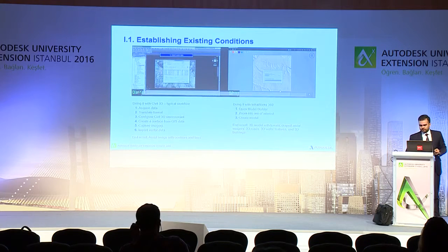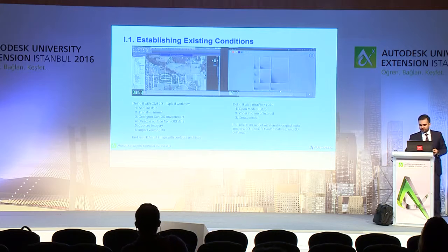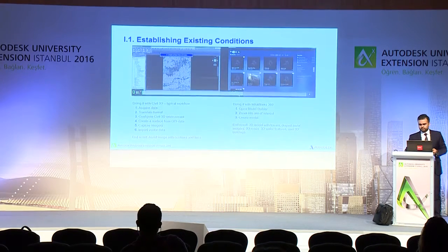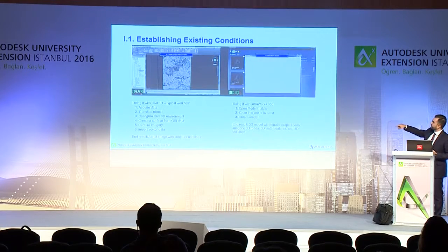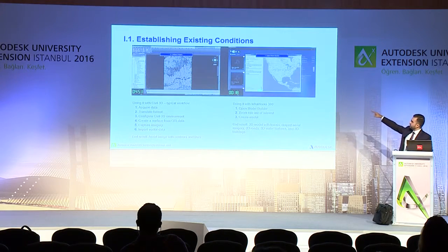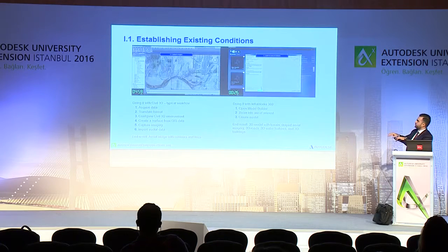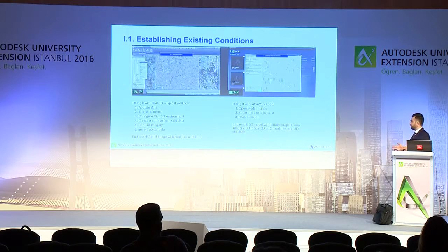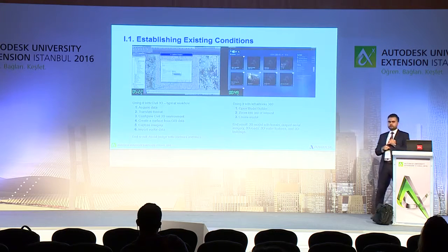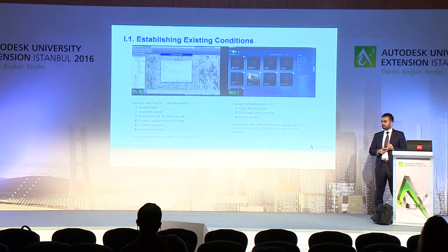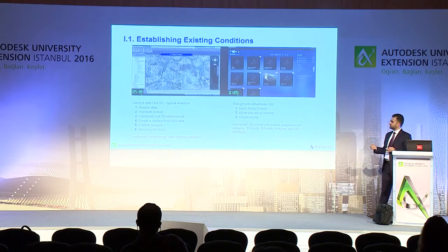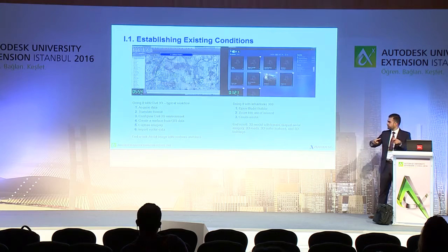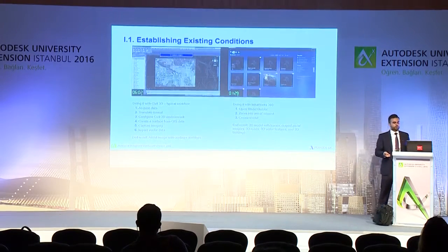I will show it. Okay. Let me go back a second. So this is InfraWorks. And inside of InfraWorks, we're going into the model builder. Very easily, we type in any city in the world, and it will create the 3D model for us. The cool thing about it, it does not require extensive knowledge about the coordinate systems and the data sources that you're pulling in. You just have to open the model builder, zoom to the area of interest, and ask the software to create it for you.